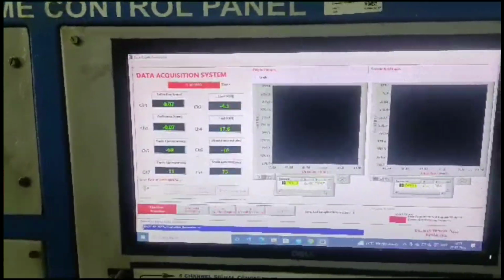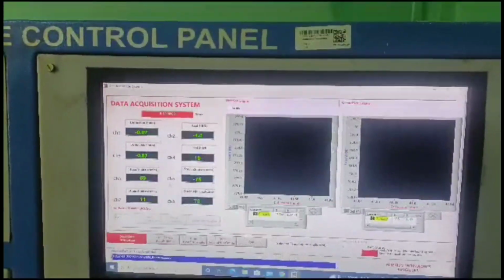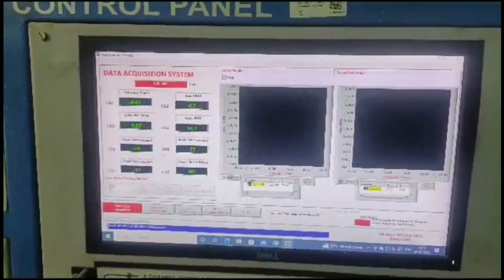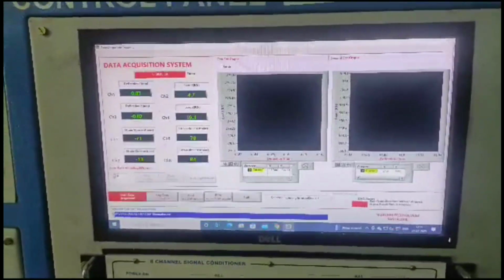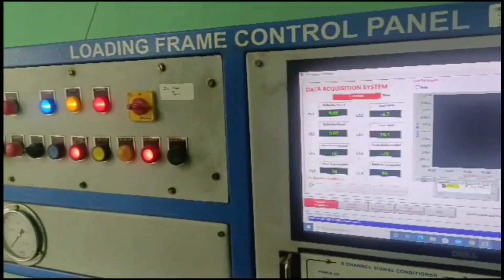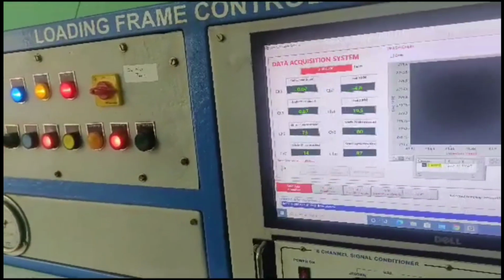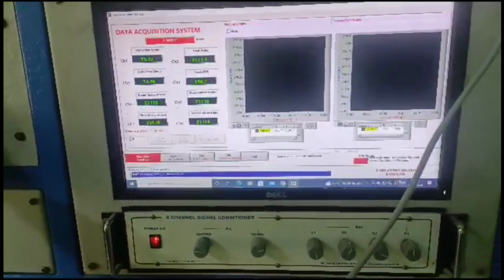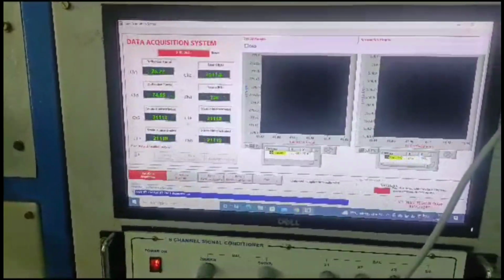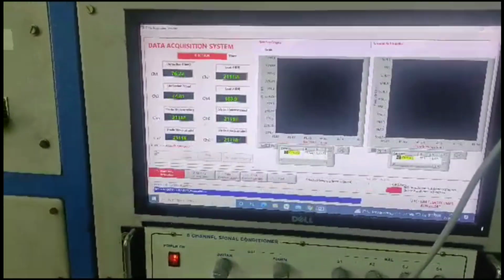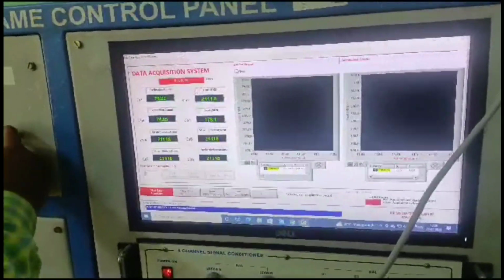So here are the methods of tests for strength of the concrete beams. The flexural testing machine bed shall be provided with steel rollers 30 mm in diameter on which the specimen is to be supported, and these rollers shall be mounted so that the distance from center to center is 60 cm for 15 cm specimens.